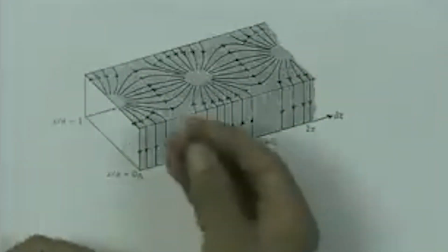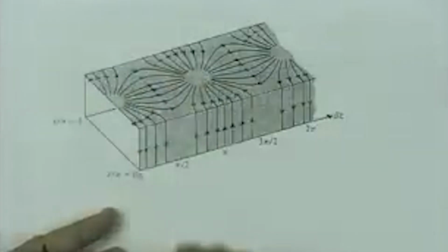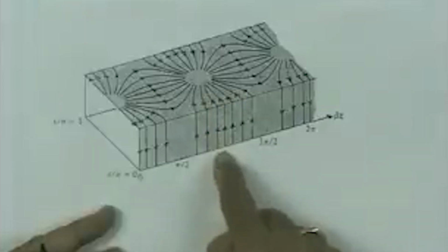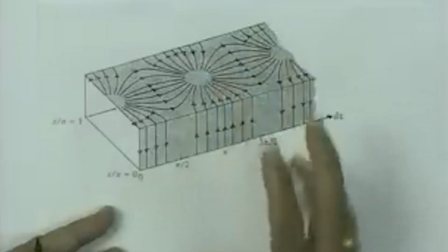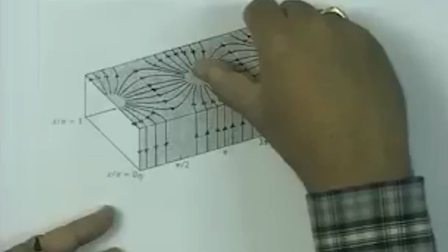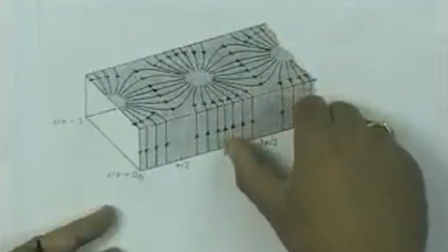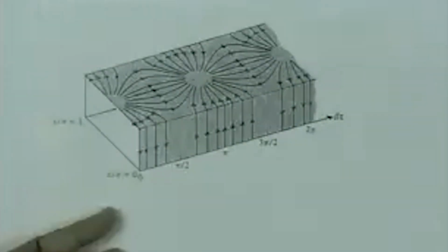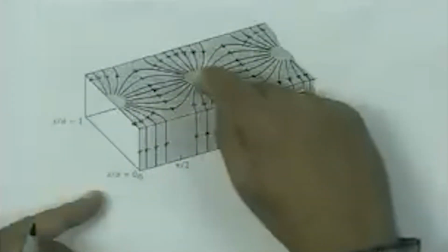So it is as if the current is just coming out of this location, flows this way, remains constant all along this wall, because it is a function of height, the amplitude of the magnetic field does not change, so the current amplitude remains constant, and on the opposite wall again the current dies down. So the current is 0 here at this center location, slowly the current amplitude increases when I come here, remains constant on this wall, and on the opposite wall again it decreases and becomes 0 on the opposite point on the lower wall. So in fact the current now is starting from nowhere, there is no source as such here.